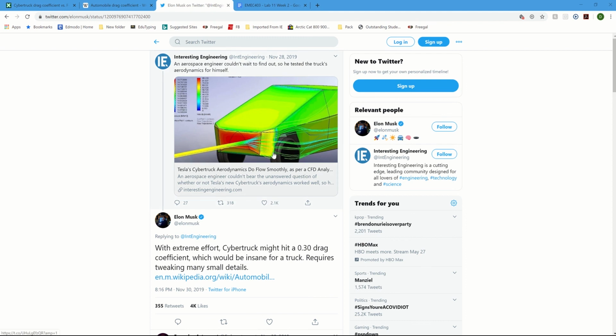What this probably means is that they would have to redesign the wheels so that they're as aerodynamic as possible. There would be no holes in the face of the wheel. They'd probably have to lower the Cybertruck. There would definitely be the bed cover. There probably wouldn't be any fender flares. And they'd probably have to change the surface of the Cybertruck. So the Cybertruck that we modeled and that other groups have modeled is just bare stainless steel, like it was announced to be. To get that more aerodynamic, you'd have to paint it and clear coat it and then put some sort of a wax on top of it to try to make it as smooth as possible.